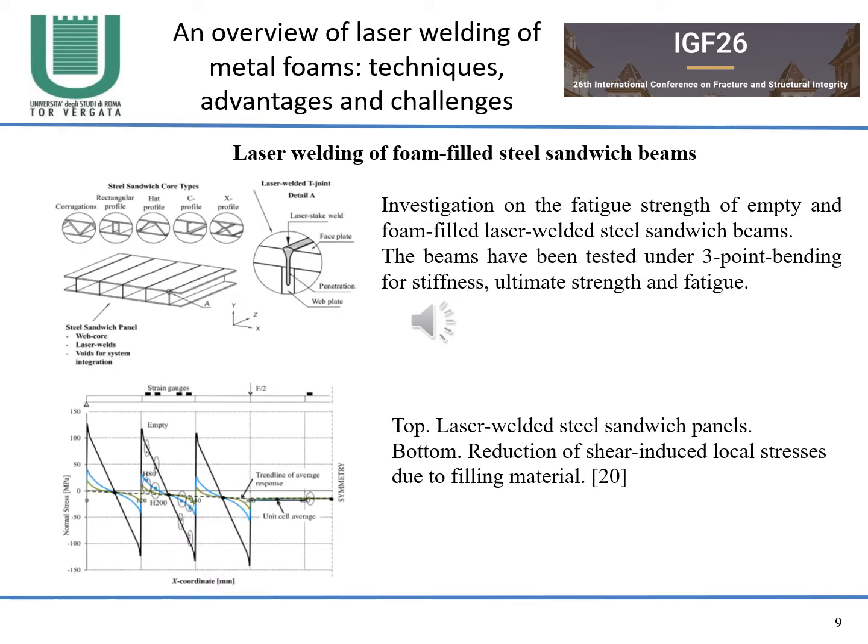In this slide, the results of the investigation of the fatigue strength of empty and foam-filled laser welded steel center beams are reported. The beams have been tested under 3-point bending for stiffness, ultimate strength, and fatigue. In the picture are reported on top laser welded steel sandwich panels, and on the bottom, the reduction of the shear-induced local stresses due to the filling material.